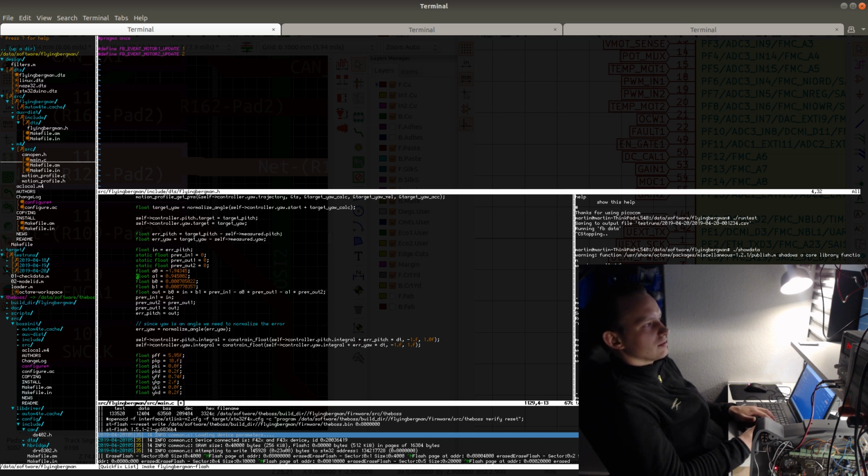I can also easily check the response time and the step response of the filter directly in MATLAB. I could obviously calculate these values dynamically based on the cutoff frequency, but I find it completely unnecessary because these are basically always constant.